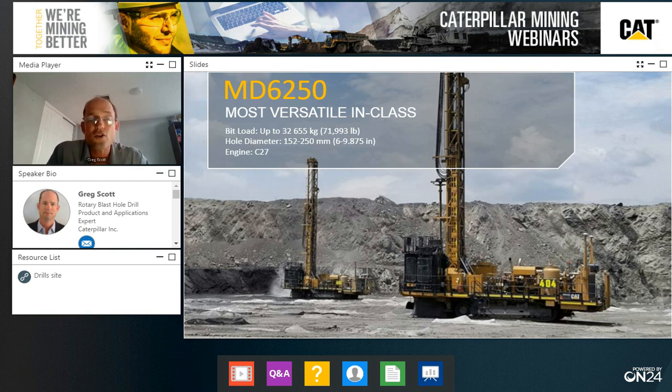For rotary and tricone drilling applications, the machine is typically configured with a 2000 CFM compressor and a mast arrangement that'll give you 36.7 feet or 11 meters single pass hole depth. If we were talking hard rock, the machine is typically configured with a DTH drilling package, which would include a 1350 CFM 500 PSI air end, plus a 13.6 meter single pass mast arrangement. That's 46 or 44.6 feet respectively. Both mast arrangements are configured with a carousel pipe rack, allowing you to drill deeper if needed.